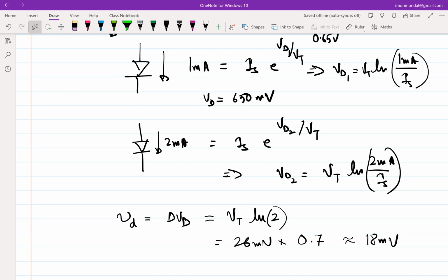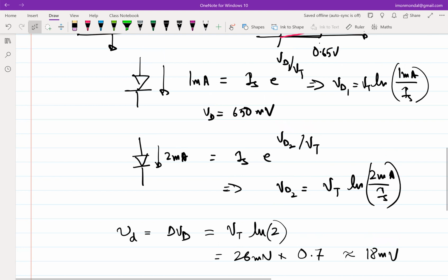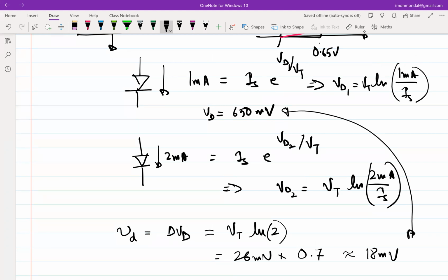So in practical scenarios, what essentially happens is that when you have a diode, instead of approximating my diode as the exact value, for example, if I start off my analysis by assuming the diode voltage to be 650 millivolts, but rigorous analysis needs it to be, let's say, 668 millivolts, how much wrong will I be? Not much, right?